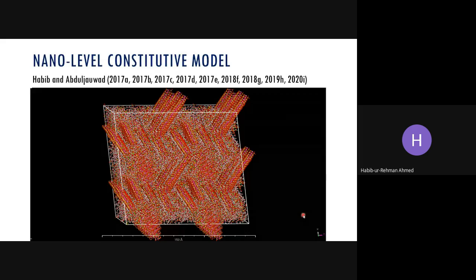And on these fabrics, we ran several things, like swelling under different confining pressures, different temperatures, and different cation exchange capacities, different types of clay particles, different initial moisture contents, different initial densities, different final densities, different types of cementation materials like calcium carbonate, calcium sulfate hydrate like gypsum, calcite, calcium chloride, and so many other variations.